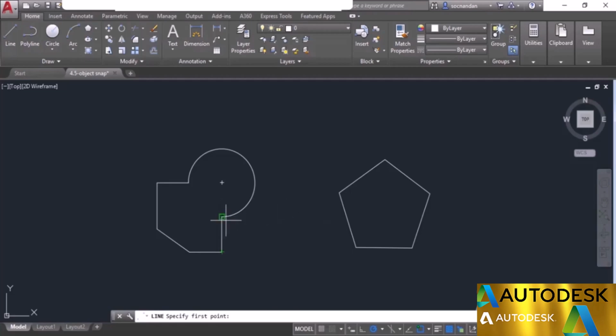So if you want to take reference of this, simply click on this object snap tracking, move back to this point, and now move in this direction, and you'll have this tracking vector. So that will take reference of the existing object snap. So you need to ensure that object snap tracking is on if you want to take its reference. Now here also I'll press enter again. I'll go to this midpoint or the center, but I'll not click, and here we have the reference. You can click here, you can take the reference in vertical direction or in any other direction.